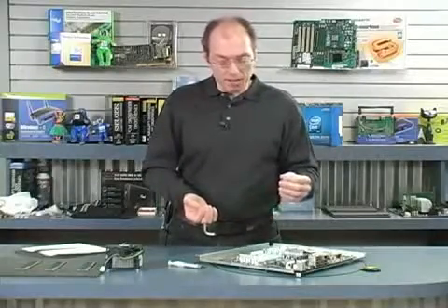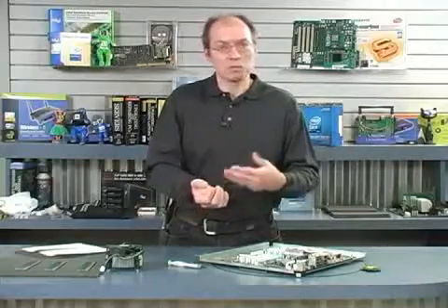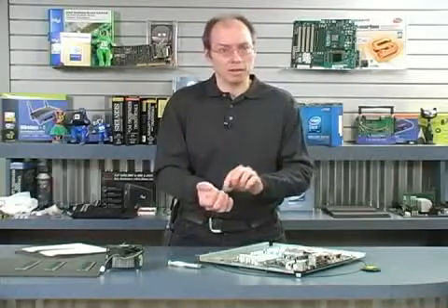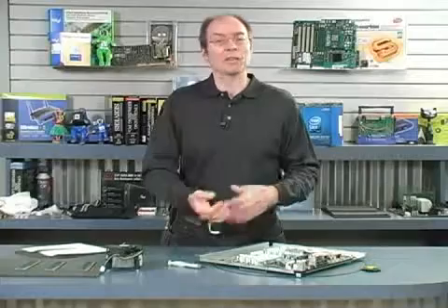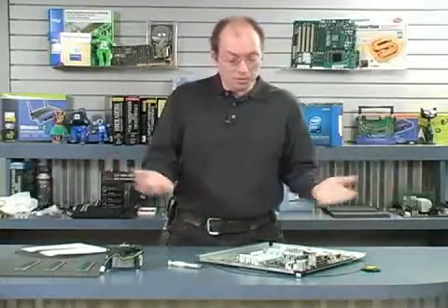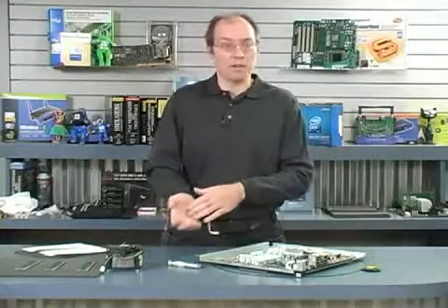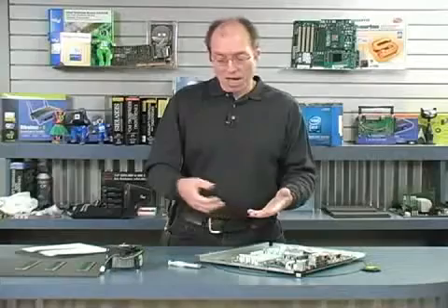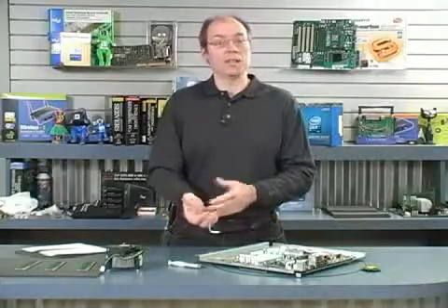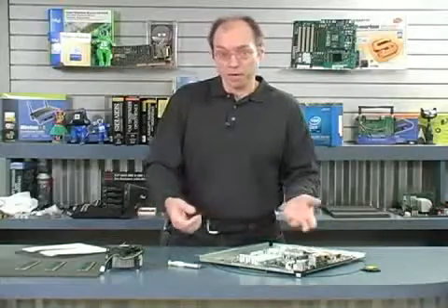The other thing that happens is it dries out. The grease usually has a silicone oil to suspend the thermal material, and eventually it can dry out. So those are some of the drawbacks of the grease, and that's why the manufacturers like to use the phase change material. I've had people buy processors that come with heatsinks and scrape the phase change material off, never even using it, thinking that the grease is better.